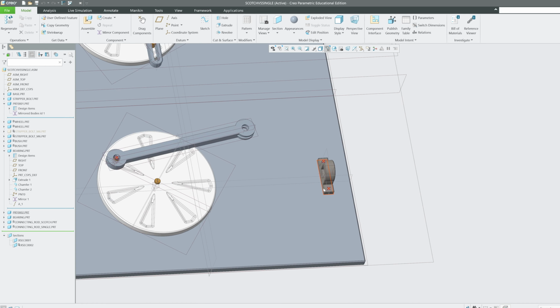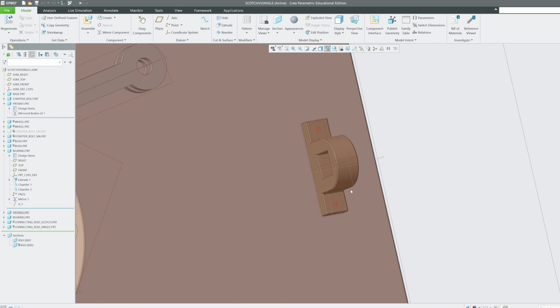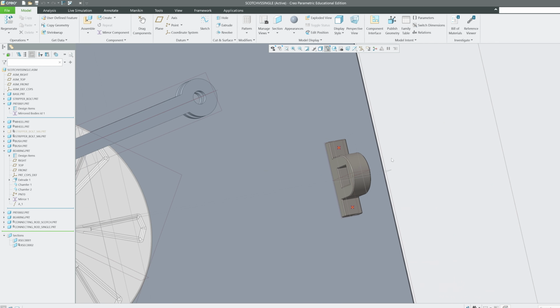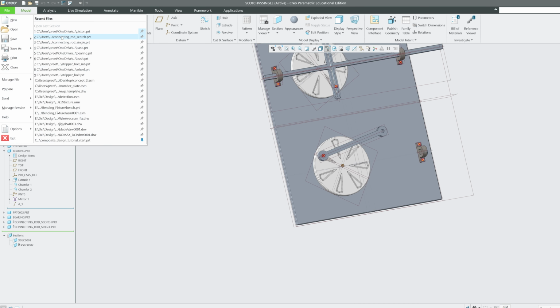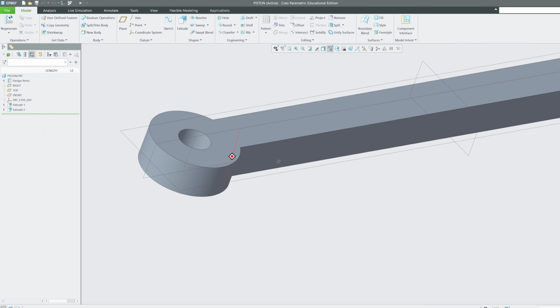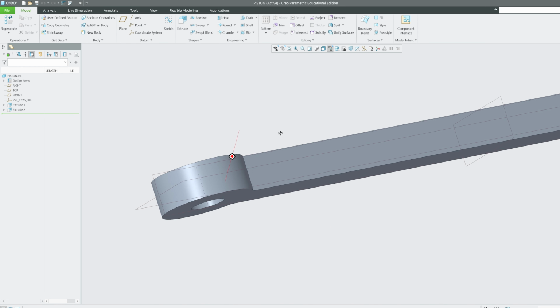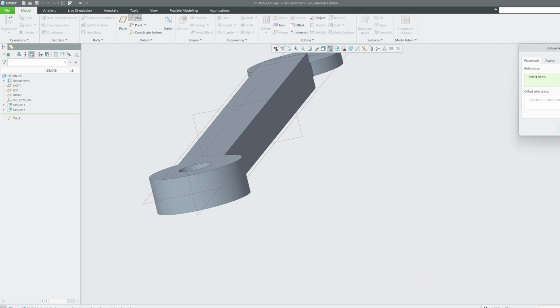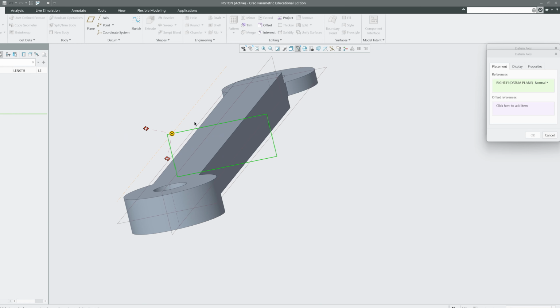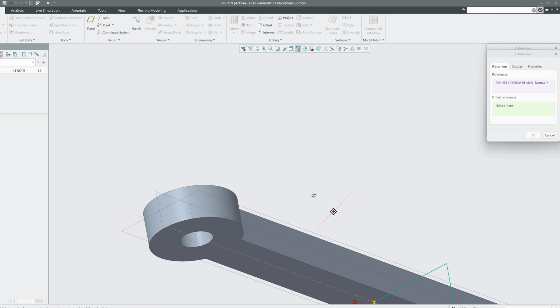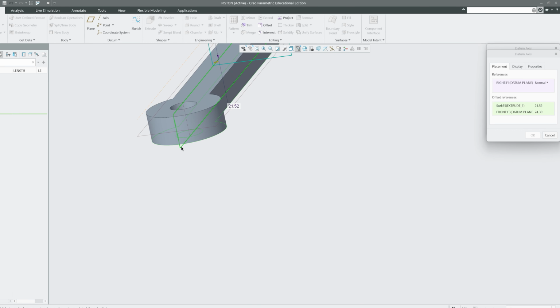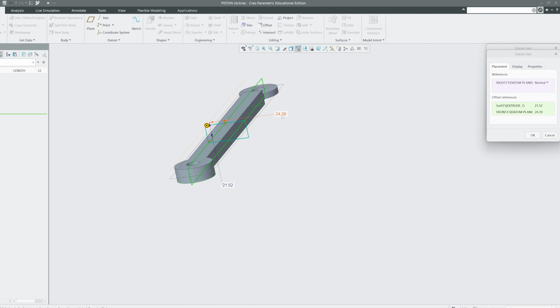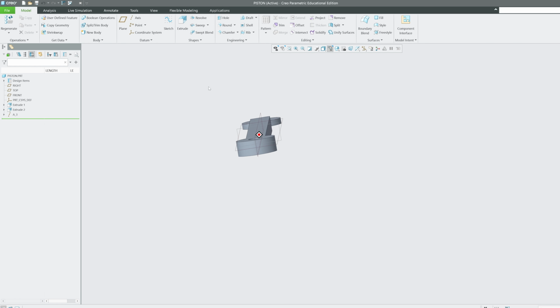And I also need to think about making it slider. Okay, so here we already have this. Now I need to have a similar kind of slider on my piston on this side. So let's have it actually. Shouldn't be tough. So let's add axis. And I'm gonna say axis, and let's offset reference. I'm gonna give this as 1, and of course this one as 1. So I'm gonna make it like 0 and 0. Yep. Okay, and what else?